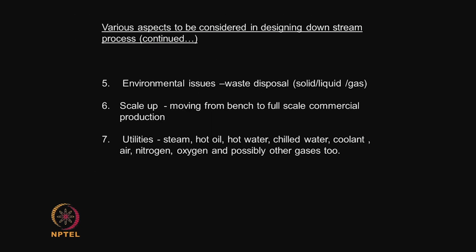Then what are the environmental issues? How much waste am I generating? Am I generating a lot of solid waste? Am I generating liquid waste? Especially in liquid extraction, I am going to have a lot of solvents being used. So, am I recovering all the solvents? Because I cannot afford to throw the solvent out. One is the cost of the solvent could be very high, and number 2 is I will be generating a lot of waste solvent which cannot be thrown out like that.